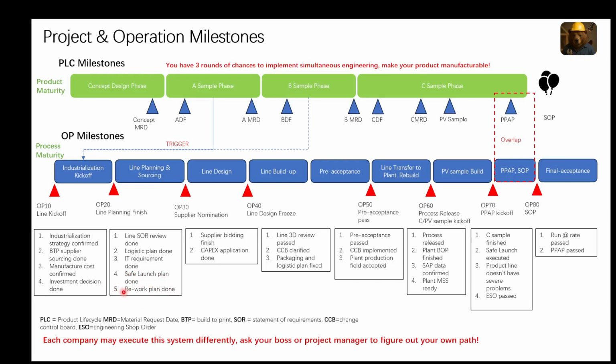A rework plan, you need to also understand that you must make sure your product can be reworked in your plant. It doesn't matter if the product is not reworkable. Yeah, if it's not reworkable, like inverter, a lot of processes are not reworkable, then so be it. If it's reworkable, like the final assembly line, you need to plan the machines, or mostly manual machines, to rework, and how the serial product line is going to react if there is an NG part. Yeah, the rework plan.